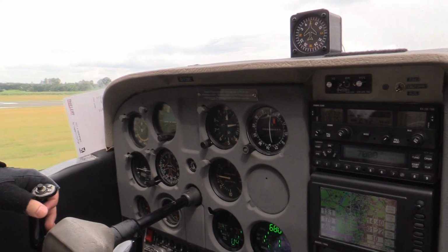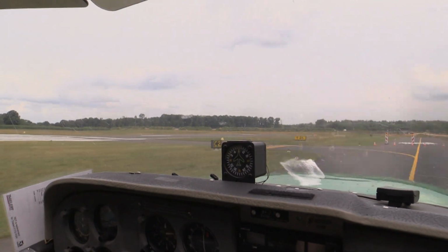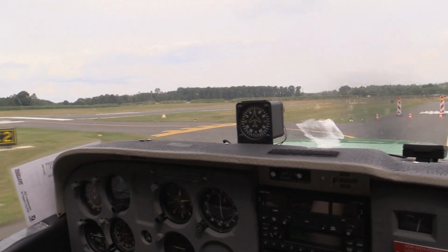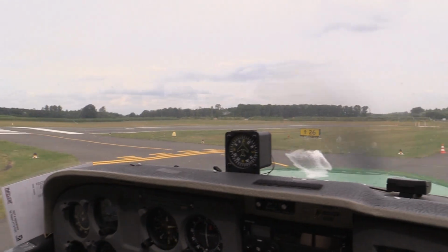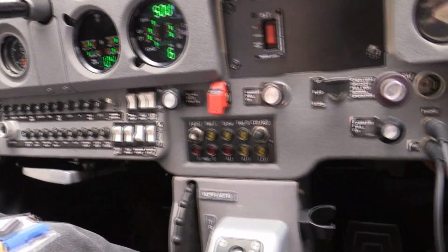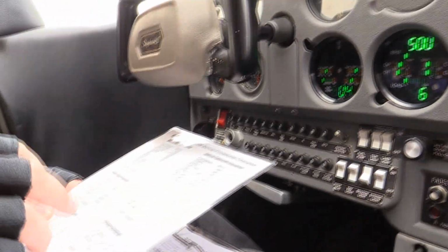Alright, now we've reached the holding point. Now what we gotta do is the run-up of our engine to check that everything is in order and that everything works as it should, and this is really easy with this aircraft as it's FADEC controlled, so all I have to do is push a button and observe what the computer is doing. But now let's just go through the taxi checklist and see that we completed all these items during taxi.